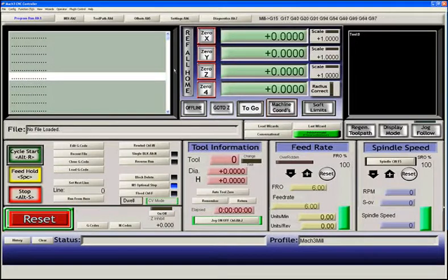If we now zero the x-axis and jog a particular distance, you should be able to measure that, and it should have moved exactly 2.1877 in this case. That takes care of the two most common problems that you're going to come across in Mach 3 and the two most common reports of trouble.